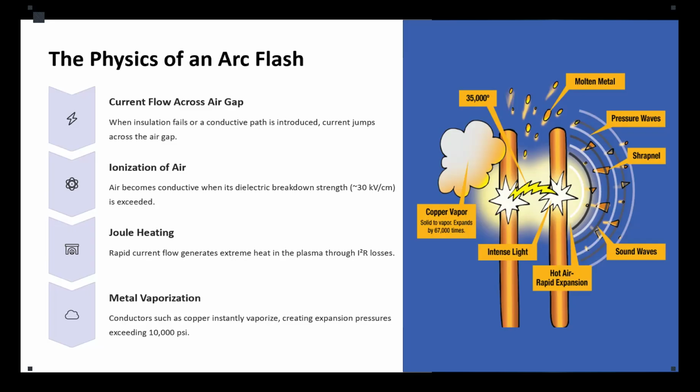In numerical terms, the dielectric strength of dry air is about 30 kilovolts per centimeter, meaning if we have a 1 centimeter air gap, it could tolerate up to 30 kilovolts across that air gap. But once the local electric field exceeds that, the air can no longer hold back the current.